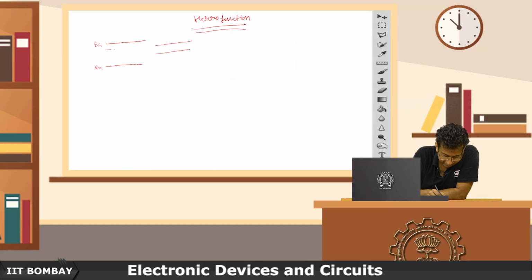So drawing these energy band diagrams, as you can see, I keep drawing these energy band diagrams, and that gives a lot of information to us, like whether the electron will flow or not. So how can we draw that? Okay, so let's consider a case where we have two different semiconductors. It's the EC1, EV1, and let's say the first one is the N-type one, and this is the P-type one. So this is EF1, this is EF2, EV2, EC2. So what are we going to do?